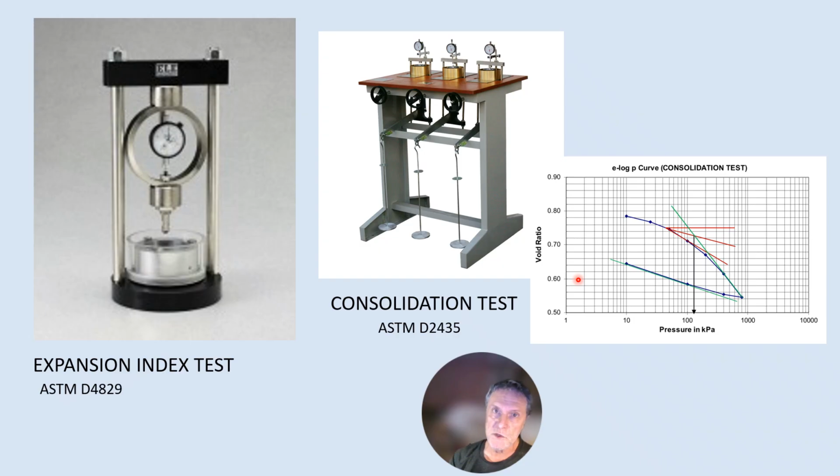And sort of the opposite of the expansion is a consolidation test. As I mentioned, there are some soils which collapse or consolidate with additional moisture. So you load the samples into these brass containers, fill them with water, and then impose additional loads and add water if you need to saturate them further, and that will give you a degree of consolidation, or volume change, or reduction in volume it has undergone under loading.